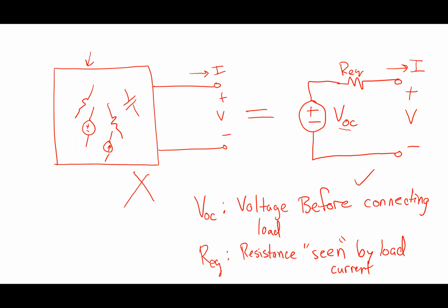That resistance there, and this is maybe the key thing, tells us the effect of what in this circuit? Why is he here? What does he tell us the effect of? It's the impedance of everything that's in that box. And the reason he affects the terminal voltage is why? Because it'll change the current. Well, because any current that flows changes the voltage, right?